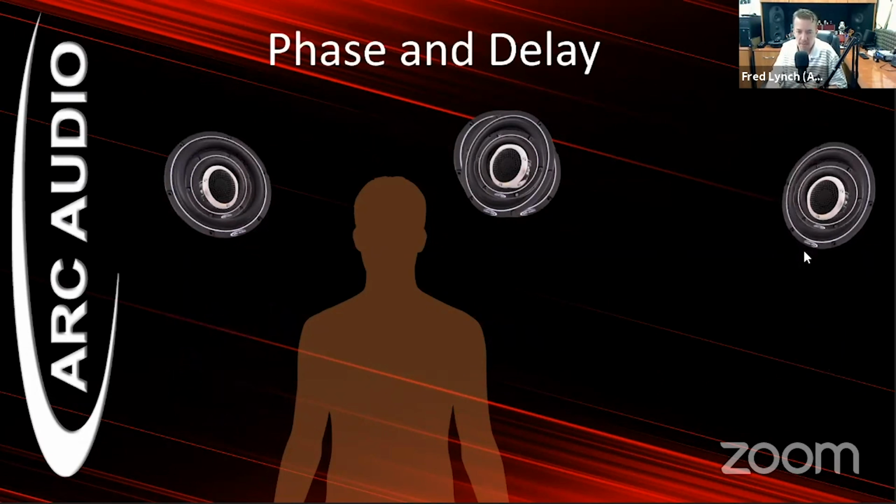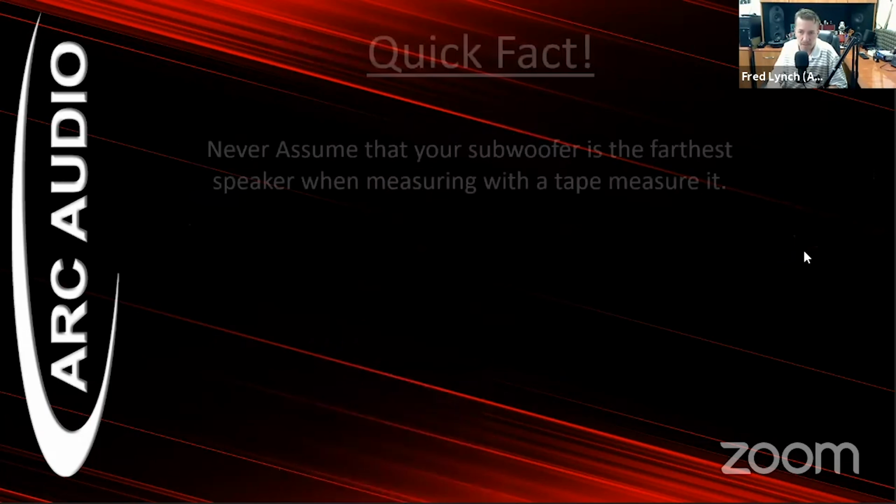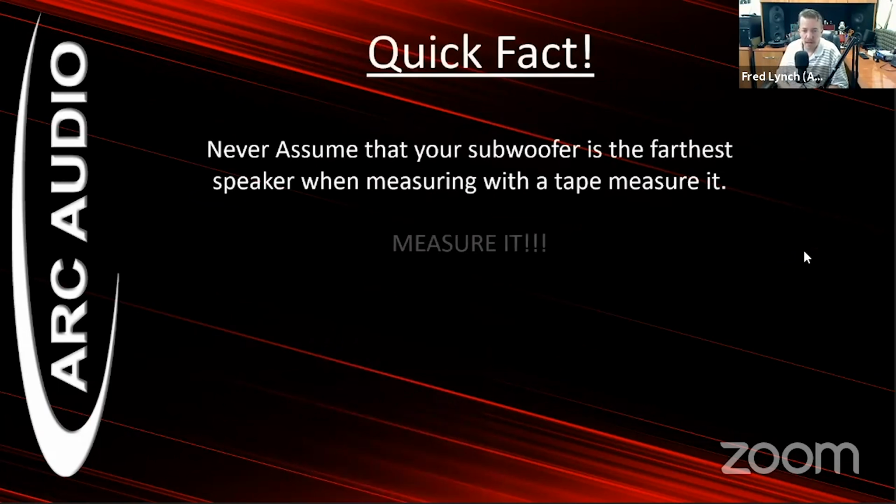And of course, you have speakers that are down low and you have speakers that are up high. So we need to make everything sound like it's coming from up top. So number one thing here, if you're doing the tape measure, just remember, a lot of people always assume that the subwoofer is the farthest speaker. You might want to measure it. In a lot of vehicles, it is not. In some cases, you will find that maybe even something over on your passenger side is actually further away than that subwoofer.